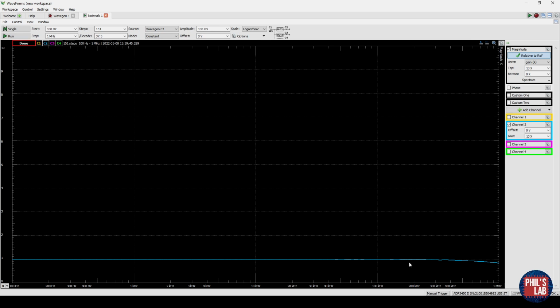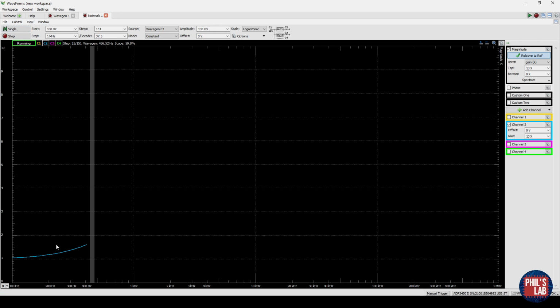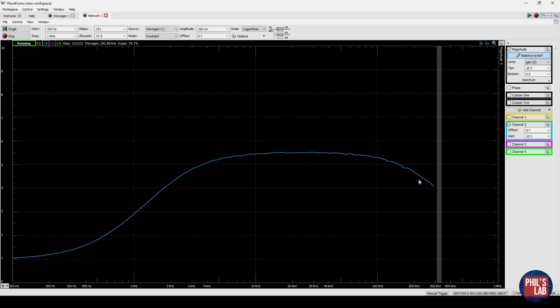But now if I, for example, center my feedback potentiometer and do another measurement, you can see I have some sort of high-pass filter over here, and then I will go into my passband, and then quite soon roll off again. So my gain at a centered potentiometer is about 5.5. So for the bandwidth, we divide by root 2, and that is just under 4, I believe. So somewhere here is our new bandwidth, which is about 350 kilohertz.